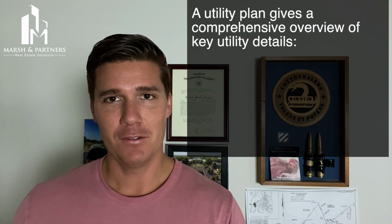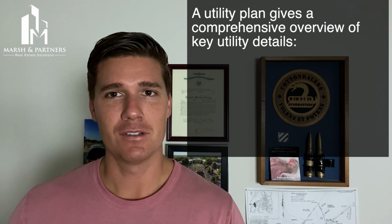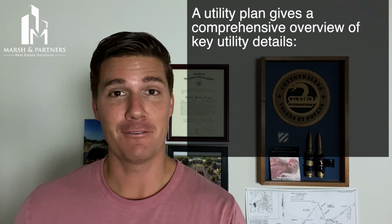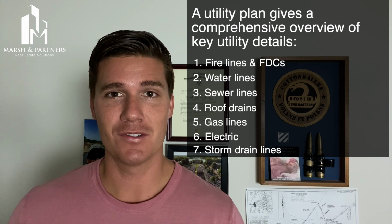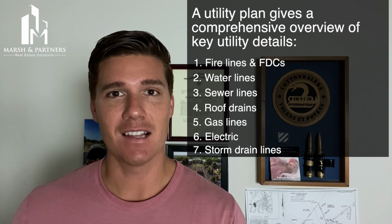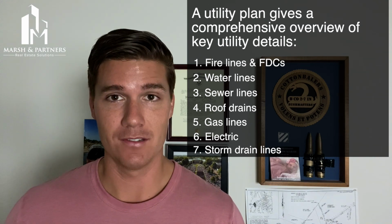Now, the next engineering construction drawing you'll find is the utility plan. The utility plan shows the size and location of all utility improvements that will be made to the property. This includes any fire lines or fire department connections, water lines, sanitary sewer lines, roof drains, gas lines, electrical lines, and storm drain lines. The utility plan directly informs the grading and drainage plan that comes next.